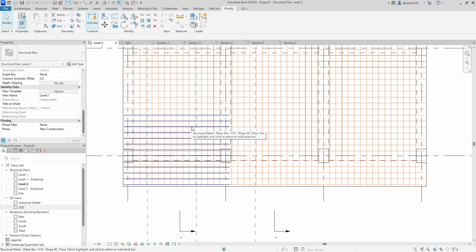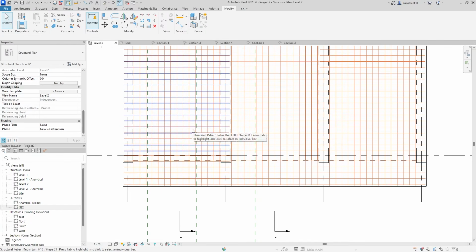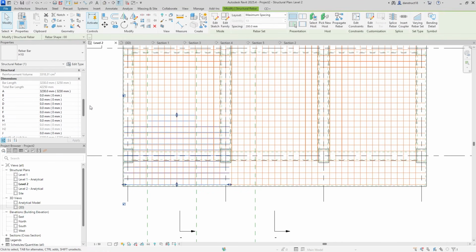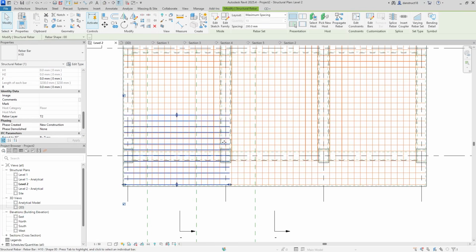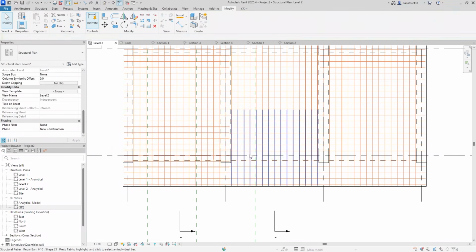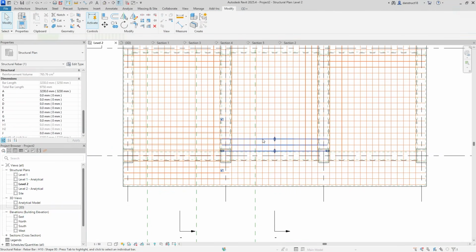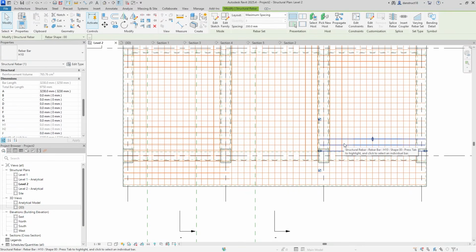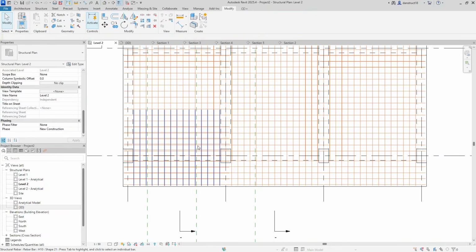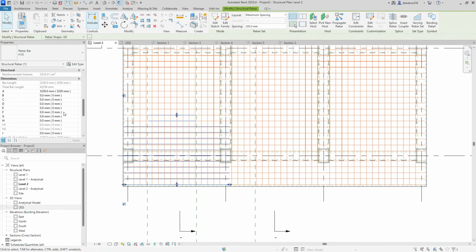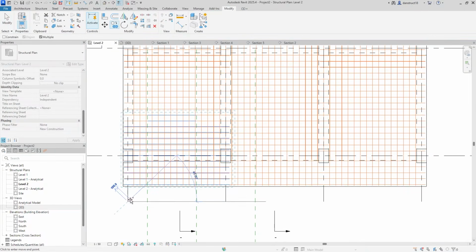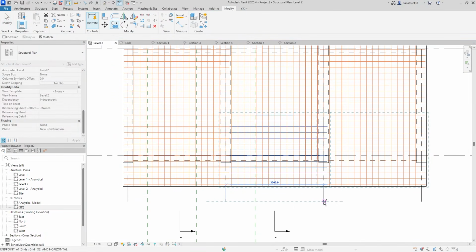We also need to modify the T2. So just press tab till I can select the T2 reinforcements. There we go. So that's T2. I'll copy here. And so I'll delete this one first. So let's just click and delete. That's the existing. Click here, delete this. So I'll just press tab and press tab till I find T2. And I'll copy. Click here, and click here to paste it. There we go.